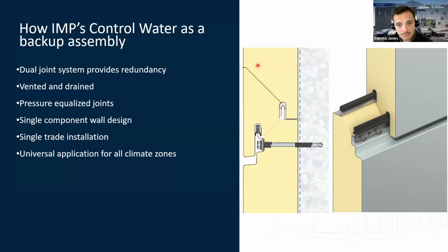Now, I already mentioned steel. It's not aluminum, it is steel on this exterior face. This is also steel. And because of that, we can essentially riddle this exterior face with all kinds of holes, and it would never affect the weather tightness because there's steel to rely on back here. The insulation itself is so high density, polyisocyanurate, that it doesn't intrinsically suck water up. We often actually leave it exposed and there's no issue with it getting soaked up or anything like that. So that's not an issue.